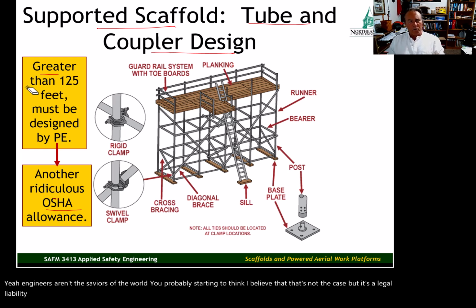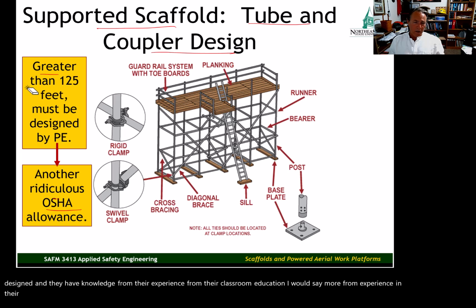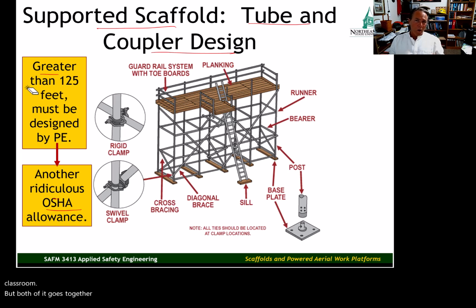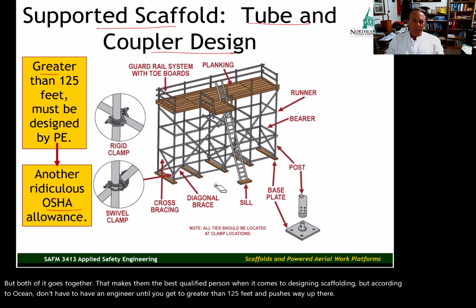And engineers also have the ability to do calculations and show that the scaffold is properly designed. And they have knowledge from their experience, from their classroom education. I'd say more from experience than in their classroom, but both of it goes together. That makes them the best qualified person when it comes to designing scaffolding. But according to OSHA, you don't have to have an engineer until you get to greater than 125 feet, which is way up there.